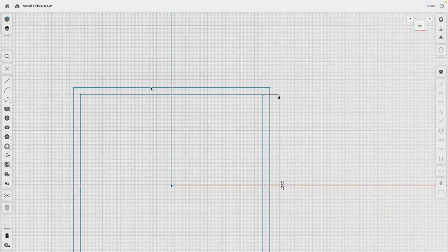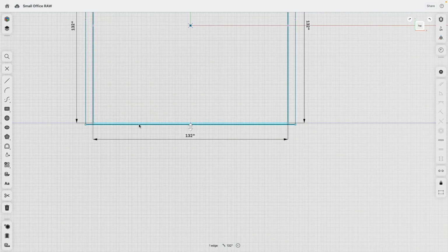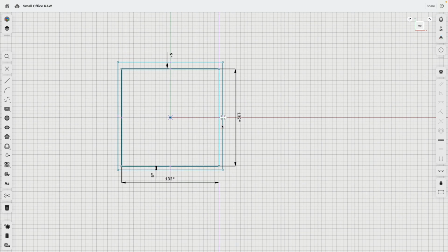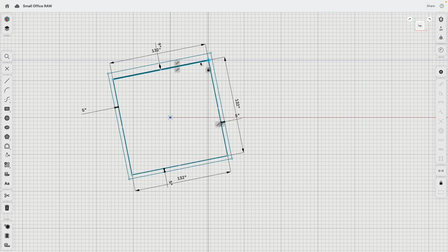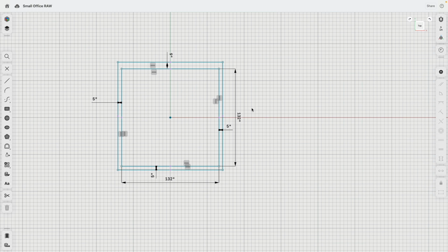Perfect. Then this is the outside wall. That has to be 9 inches because it's thicker, more insulation. That moves this wall. We push this back by giving this 5 inches. These are actually 5 inches and they are 5 inches too. Everything is drawn from the center. We still can rotate everything. So select everything and say horizontal, vertical.